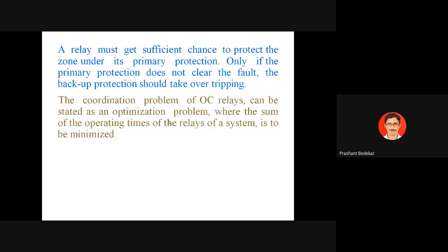The coordination problem of overcurrent relay can be stated as an optimization problem, wherein what should be the objective? The sum of the operating times of relays of a system is to be minimized. Why is the operating time of relays to be minimized?